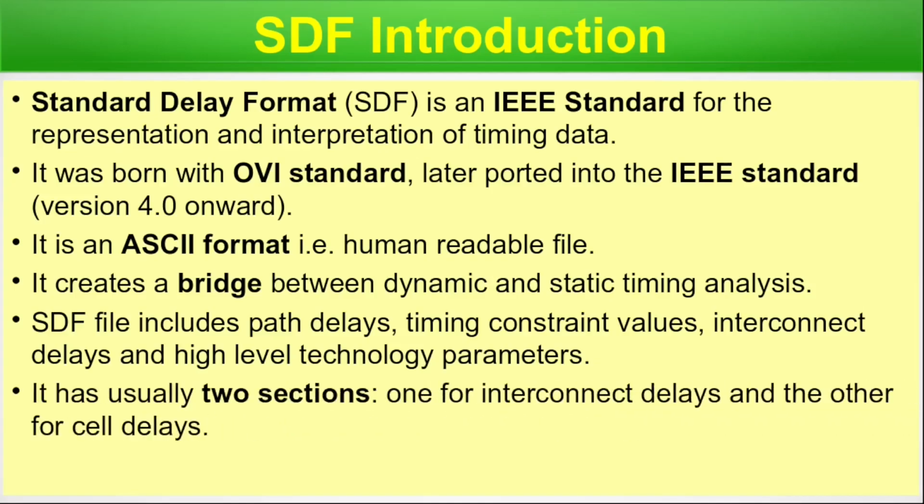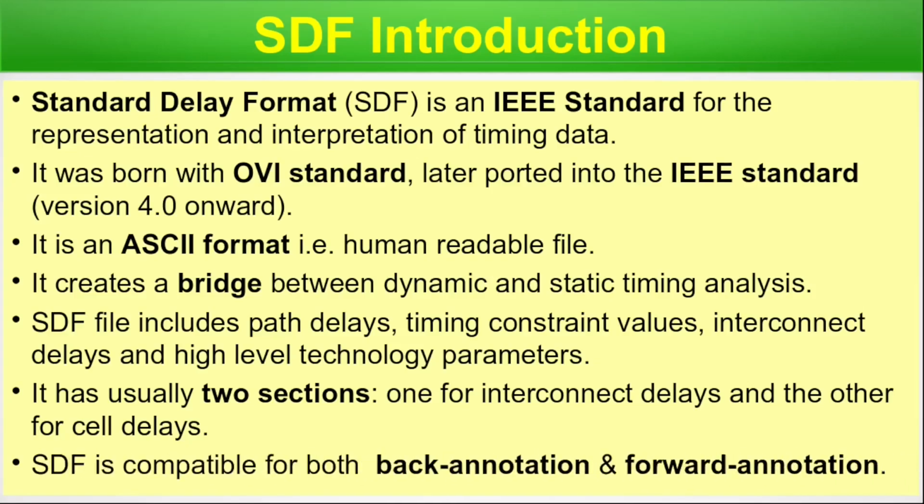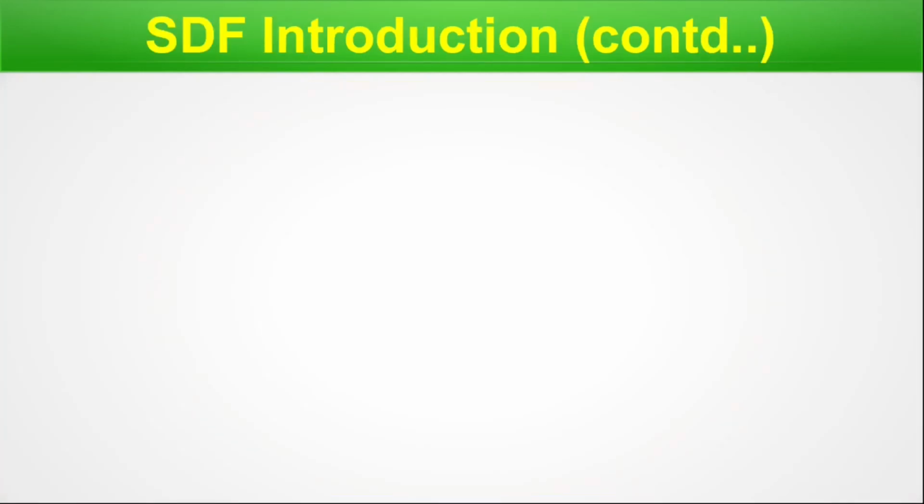It usually has two sections, one for the interconnect delays and the other for cell delays. SDF is compatible for both back annotation and forward annotation. So we are done with this particular slide, so let's move on. We continue here. Let's complete the biodata of the SDF file in this slide.